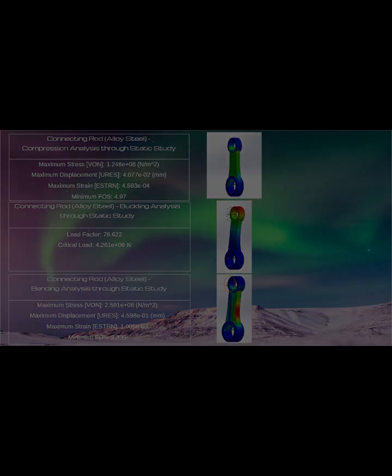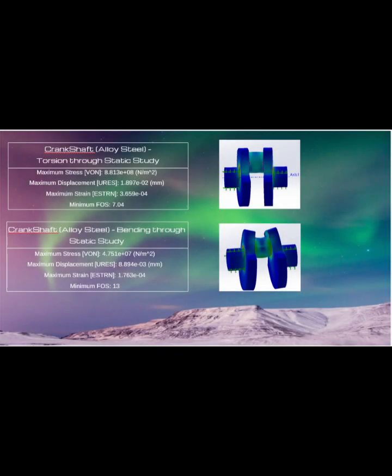The crankshaft was analyzed under two conditions, bending and torsion. For bending, the crankshaft was analyzed with the piston at top dead center, and for torsion, the crankshaft was analyzed 90 degrees off of top dead center.